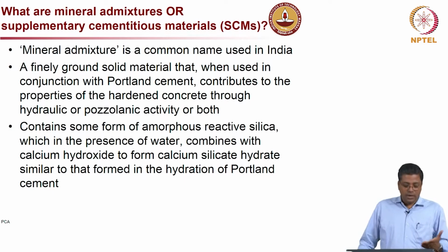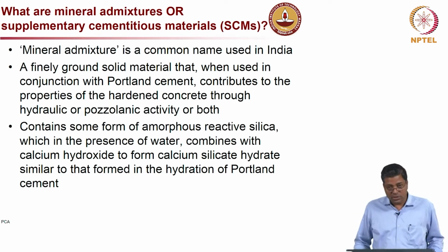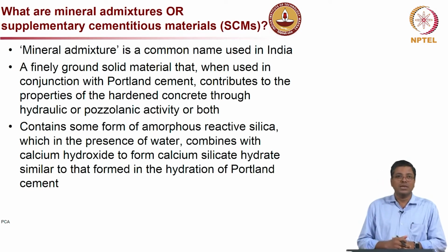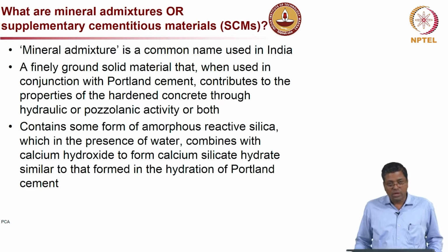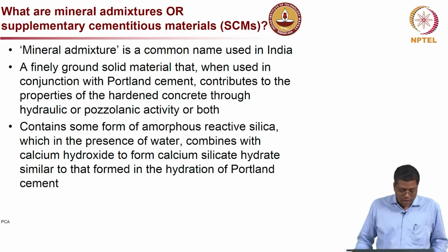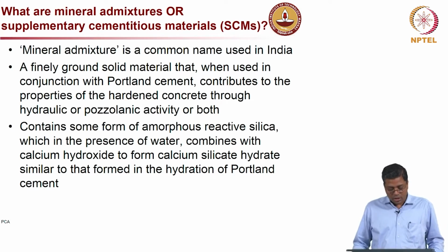Now, what are mineral admixtures? First I would say that mineral admixture is actually a common name used in India, but not outside the Indian border. Outside, the more technically correct name is supplementary cementitious materials or SCMs. So, I would like you to talk in terms of SCMs, especially when you start writing documents, and not the mineral admixtures.